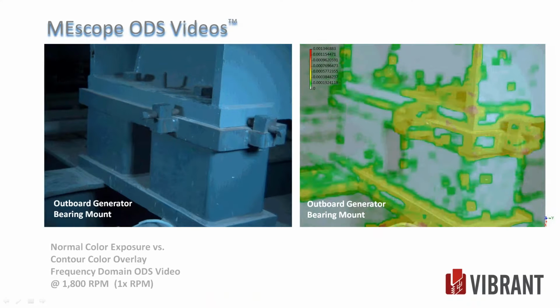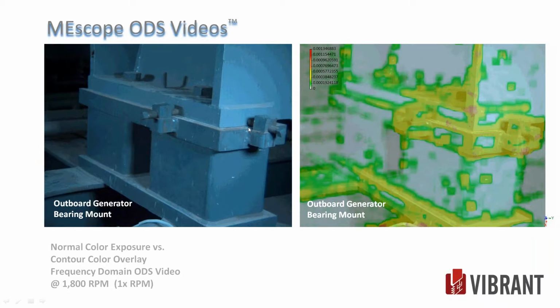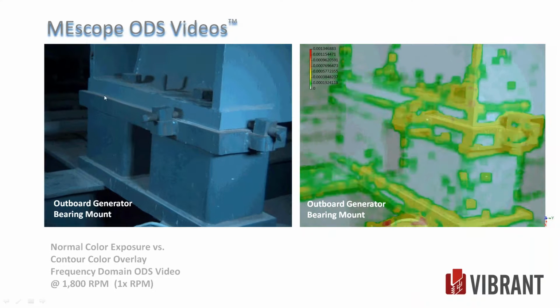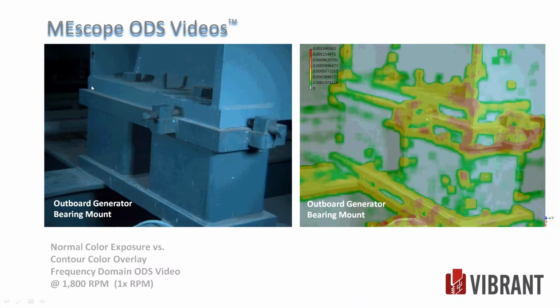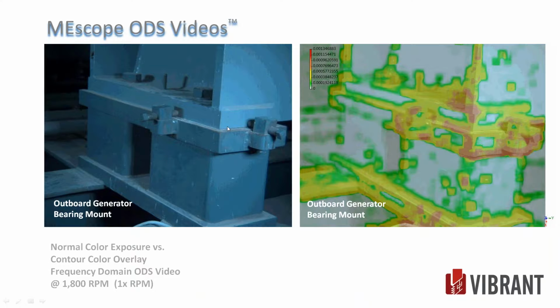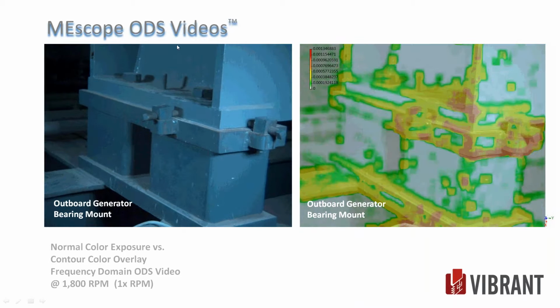We checked the mounts. So this is the outboard end of the generator. We're looking for any liftoff here. This is a shimmed controlled surface all the way around. Everything was moving in phase. We got bolts in here. Everything's bouncing up and down.